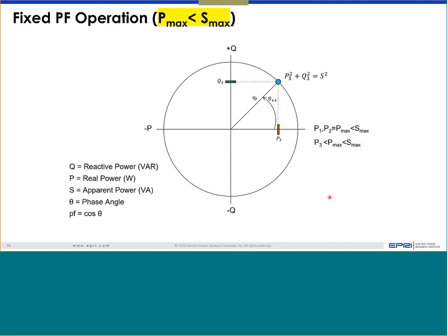So this is what I was referring to: using a too aggressive power factor may help you with the voltage, but one consequence is more active power generation loss. And later I'll show that it also means that the plant will absorb a lot of reactive power. So where will that reactive power come from? That will be another question.